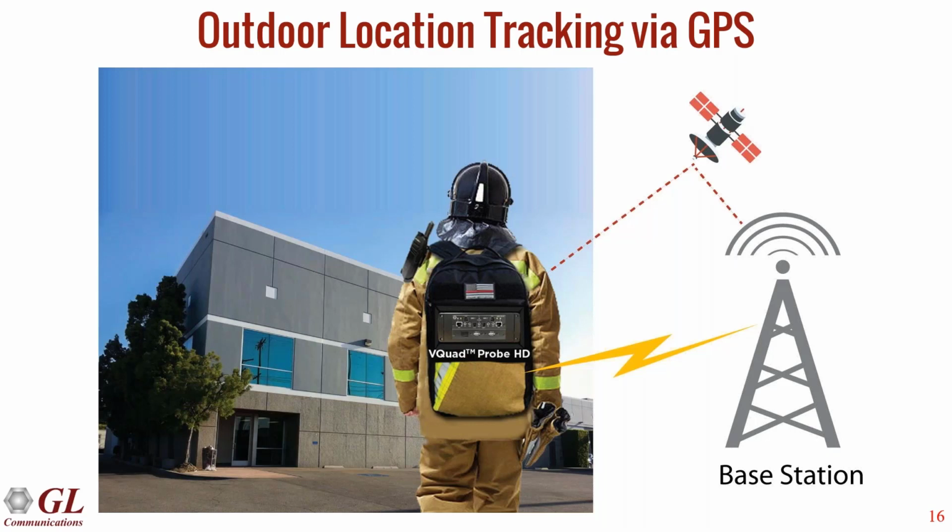So you can just travel, or you can drive, and the test will be automatically running, generating the MOS with the GPS location, GPS lat and long. The files created at a particular point will have the location information as well as the MOS, so that when we plot it, it will be very helpful for the user to identify what is going on and how the score is on this particular route.